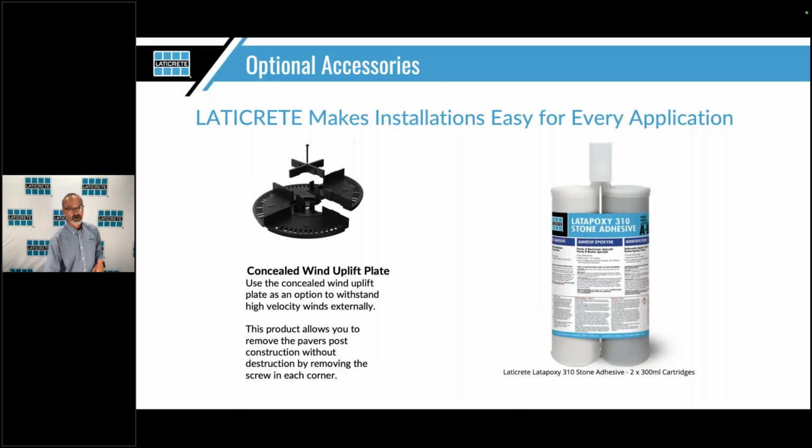Next thing we're gonna talk about are concealed wind uplift plates. So this one's in its entirety. What you'll do is use the 310 epoxy. I don't have any 310 epoxy here to show you, but you would apply it in these corners, set your finished material on top of it, and that's going to hold it down because it actually clips in just like the other ones that I've been showing you.